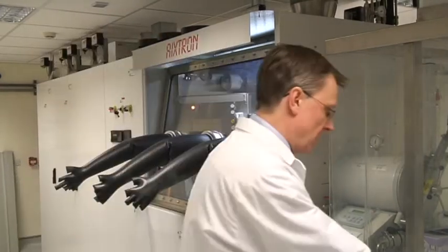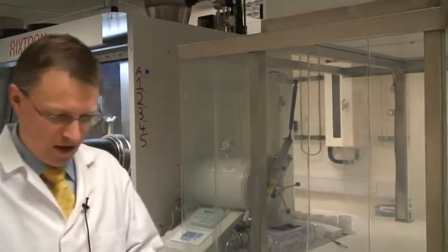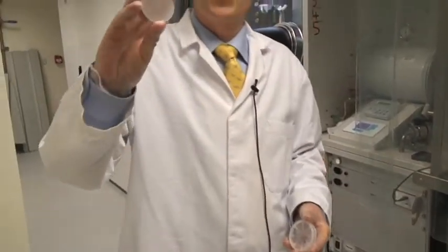Using that, we can grow wafers such as the following. This is a wafer of silicon doped gallium nitride, which is N-type. As you can see, it is a sapphire wafer and you can hardly see anything on the surface because the layer is smooth on the top. If you were to look very, very carefully, you would actually see interference fringes due to the thickness variation.